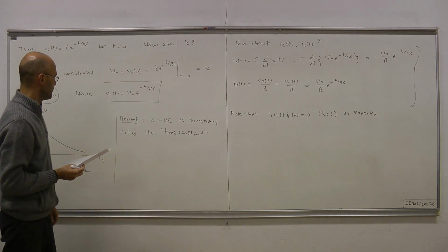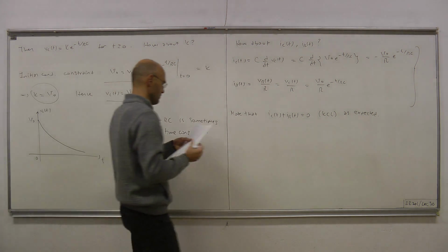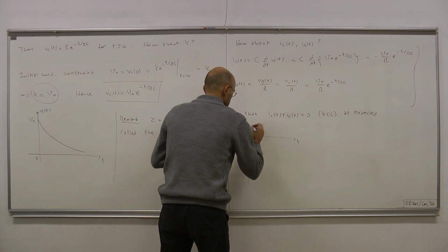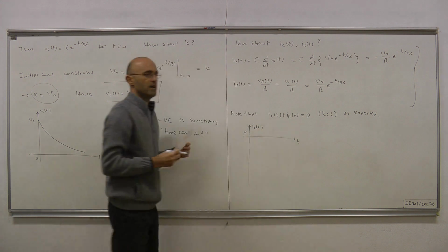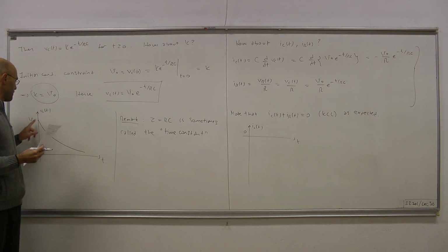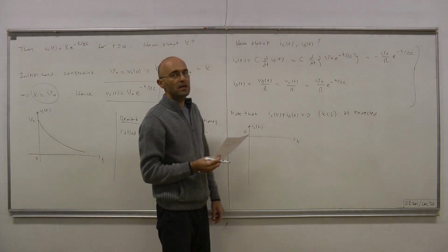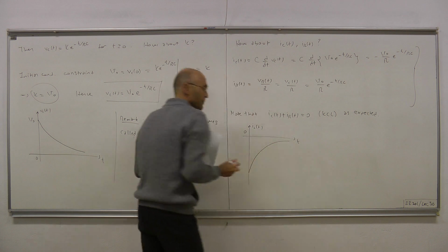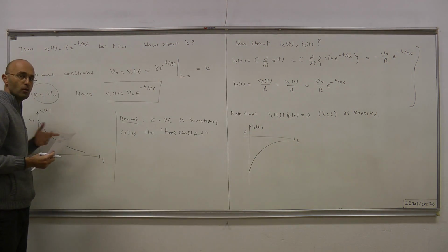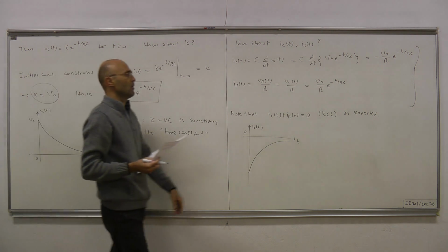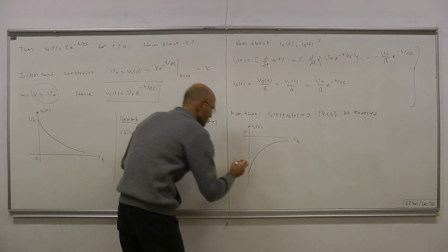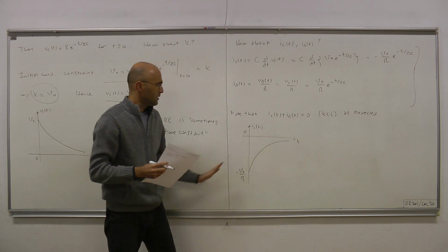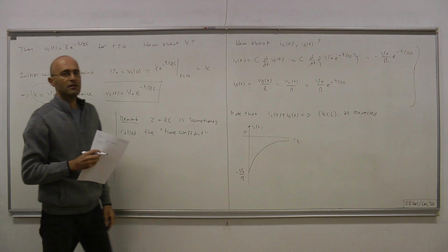Okay. How about those waveforms? This is ICT. If, as we did here, we take V0 to be positive, then IC will be negative, and it will have a similar shape to VCT, only it's upside down and scaled by 1 over R. So we start from minus V0 over R, and this current is decaying toward 0.